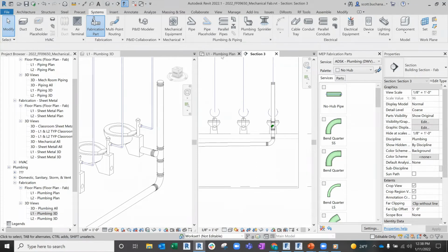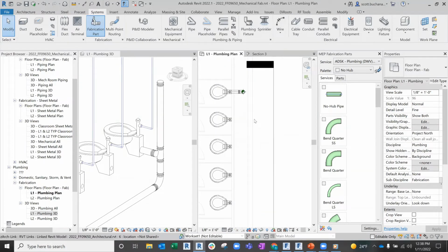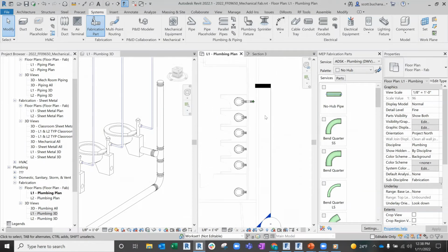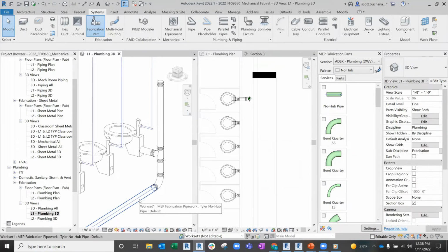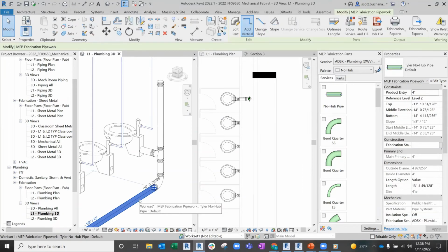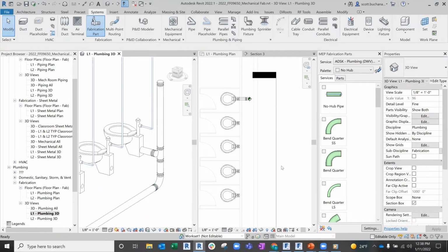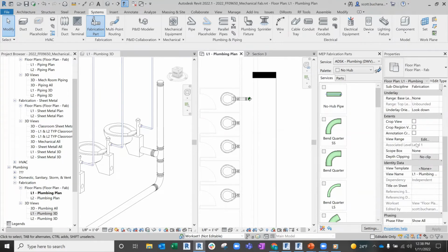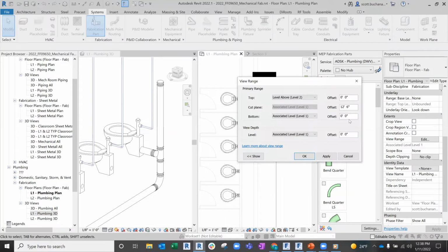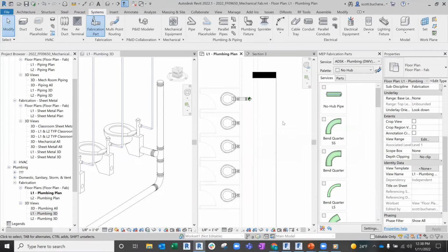And then if we wanted to finish connecting into it, again, I'm not going to try that from a 3D view. I really don't think that you can, but this is definitely where I'd go back to a 3D view. So if I look in here, now this particular, let's see how low did I drop down? I'm at there from that level. So let's drop down our viewing so we'll be able to see that pipe. Yes, let's go down just a little bit. Right, because we're under that slab there, so I'm on level 2, so I can't see anything down below it.